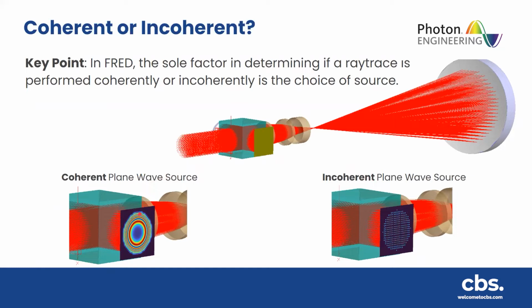Whereas in the coherent case, every ray that you see here in the 3D view, these red lines of the rays being traced, is actually a small Gaussian beamlet, as we mentioned, meaning it has a width in space. And it's those Gaussian beamlets that hit the detector, and there are quite a few of them, and they all coherently sum. And it's that coherent sum that allows us to understand the interference pattern. And that's what we don't get in the incoherent case.